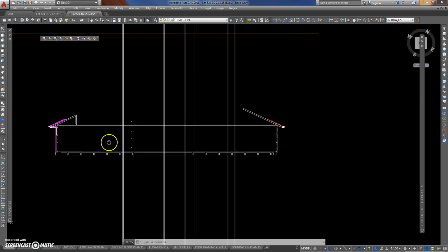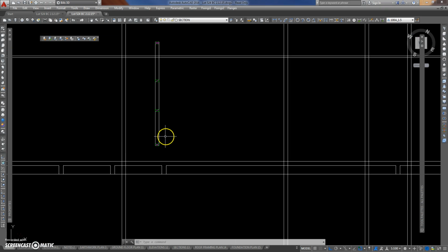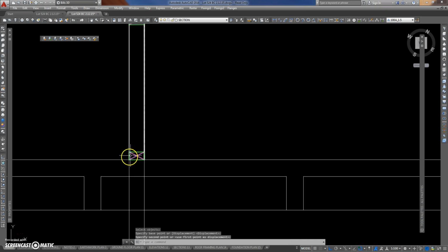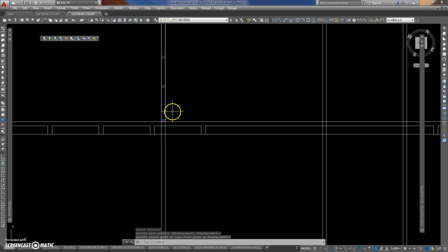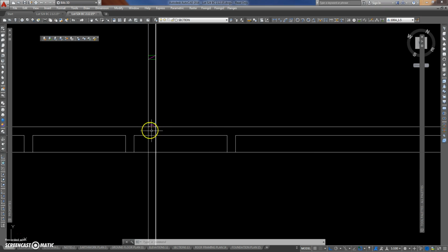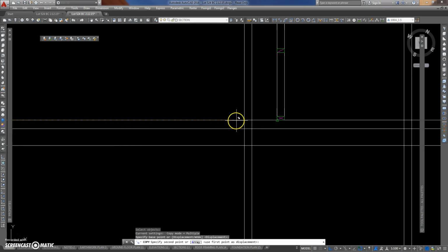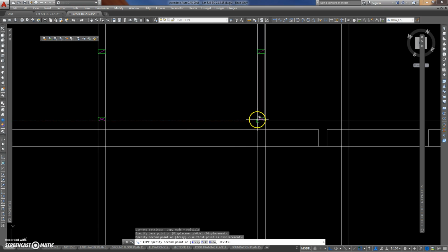Okay, so we're going to just drag and drop this section of wall here. Now we're just going to put it in the right place. That sits right there. Notice it's a 90mm wall. Sometimes they have thinner walls, but in this particular house, all the walls are 90mm. In New Zealand, that's what we do. So we just have to copy that very quickly off to the other places that it appears at.